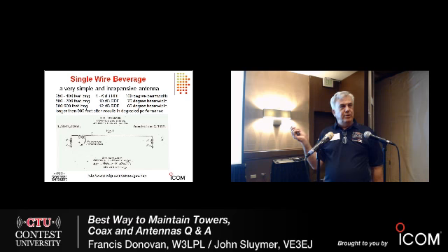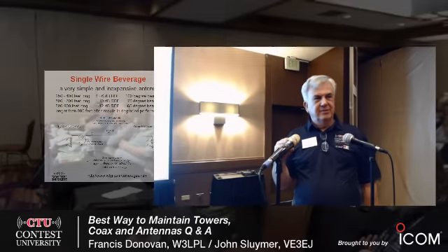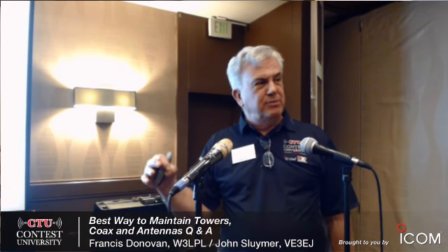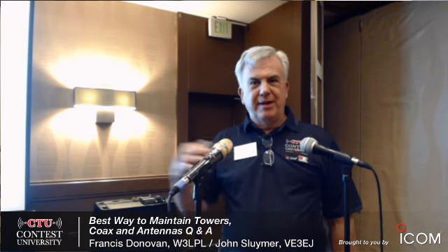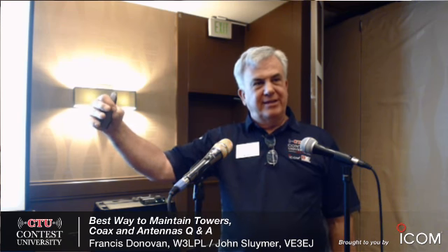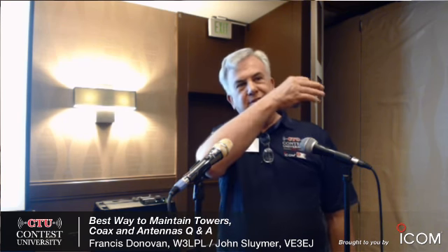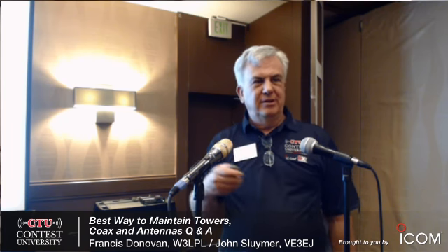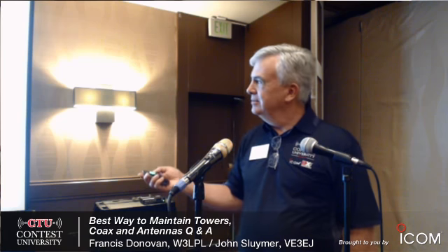The Beverage antenna, because it's so close to the ground, has a slow velocity factor. Not as bad as, but similar to coax cable. So when you make the antenna too long, the signals arriving at the antenna towards the end are in the wrong phase relationship with the signals arriving closer to the feed point. So there's a limit to the length of the Beverage, and on 160, it's about 900 feet where things start to degrade. But not many people are worried about that.